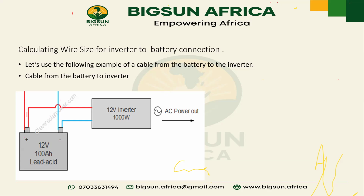Can I say something as well? Yes, Mutin. The first person said that we are going to connect in parallel. Yes, that's how we do it, because the batteries are 12 volts and this inverter is 12 volts. But about the AC charging, it will be affected because of the 4 batteries. It will slow down the charging rate.